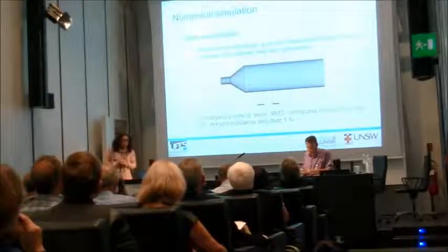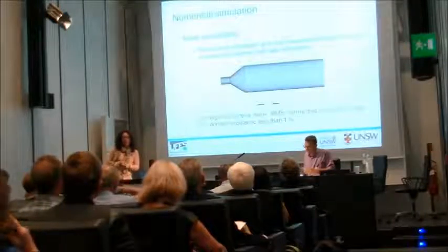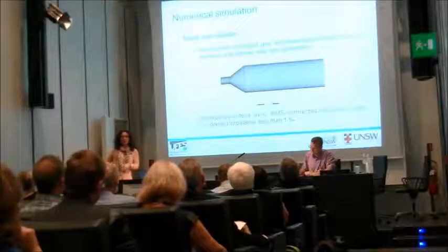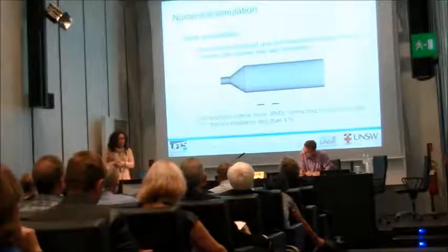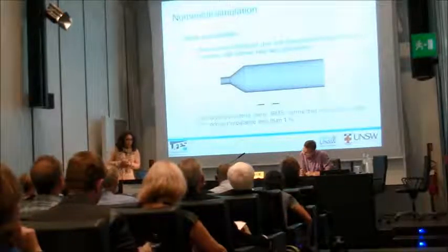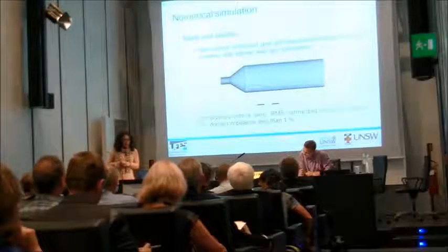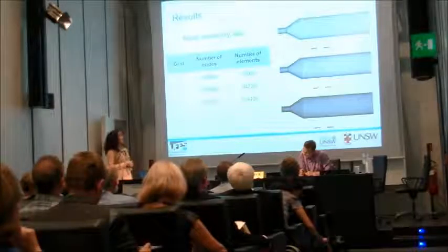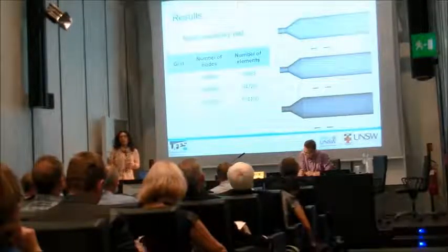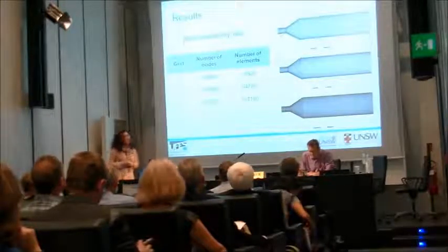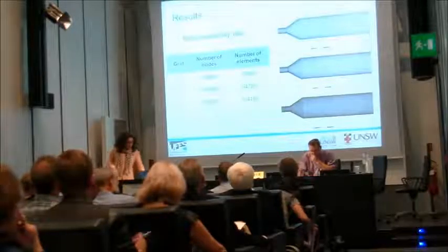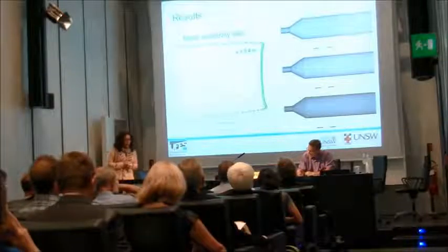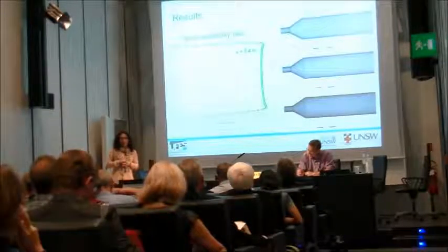As you know, to run a numerical simulation, you have to test your mesh, unless you are doing large eddy simulation, which is another thing. It's tricky to test the mesh there. So we refined the mesh as much as we liked to see if the results would change with the mesh refinement. It didn't, or actually it did, but by a very small percentage.